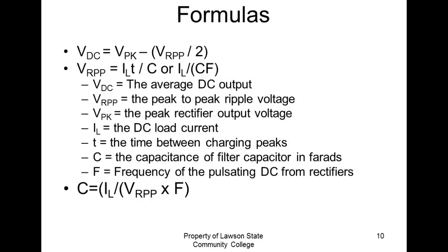So here's our formula. This is the one I like to use, because on the other one you have to figure out the time. That's where you'd use the 16.7 milliseconds for half wave and 8.3 milliseconds for full wave. But here, all you have to know is the frequency of the output pulses, not the input pulses, the output pulses.